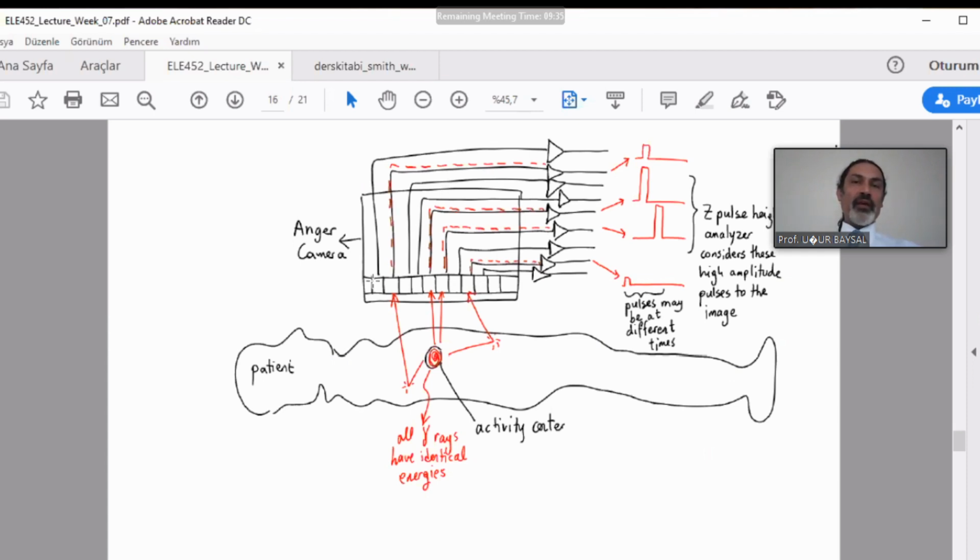This is a big cylinder and lots of electronics from each photomultiplier tube, and each amplifier is a logarithmic amplifier stage, electronics identical. And you see, look, this is the organ, and assume these are valuable rays, and this, as in PET, positron emission, is a scattered ray. This one is scattered, this one is scattered, these are not scattered. So the information here is wrong because it assumes that it receives the same thing as here, but actually not.